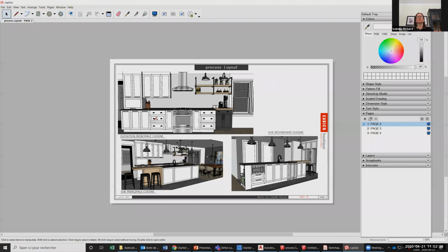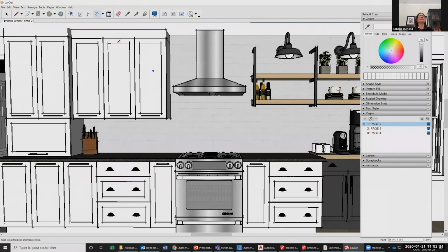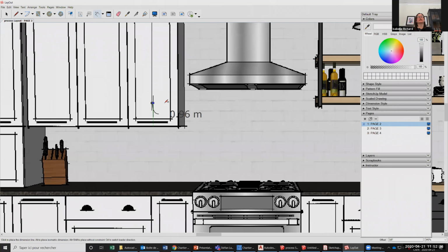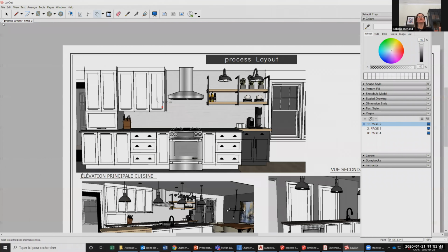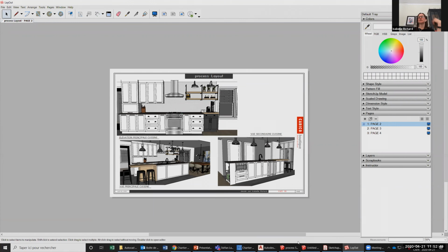I have to put a scale on it, but let's say, for example, I'm connecting it. So I can just add my measurement here instead. But one of the cool parts of this thing called Layout from SketchUp is that you can change your original drawing, and it will also change in this little sheet, because when you click on your separate view, you can change the point of view.